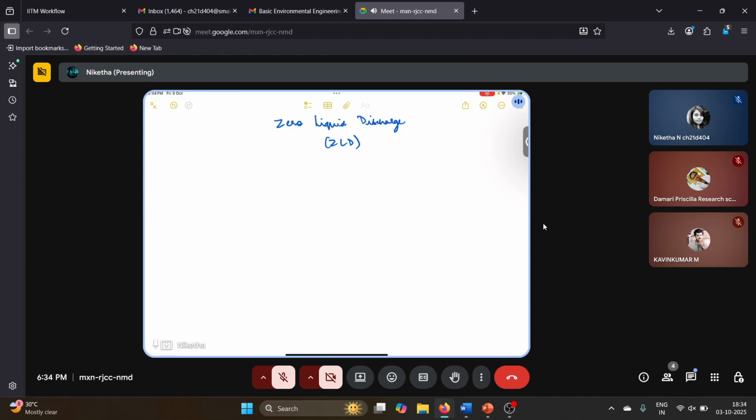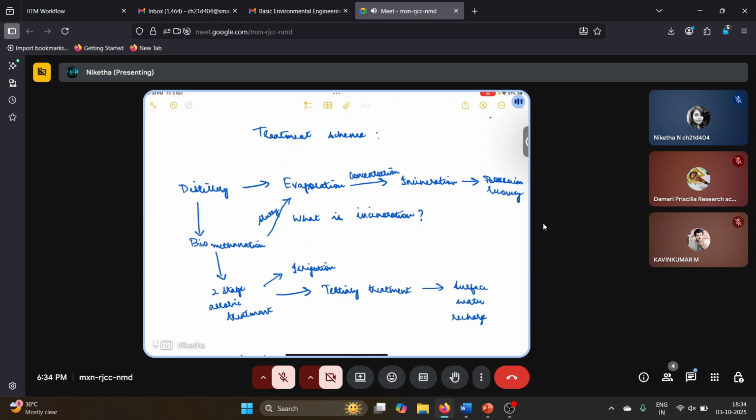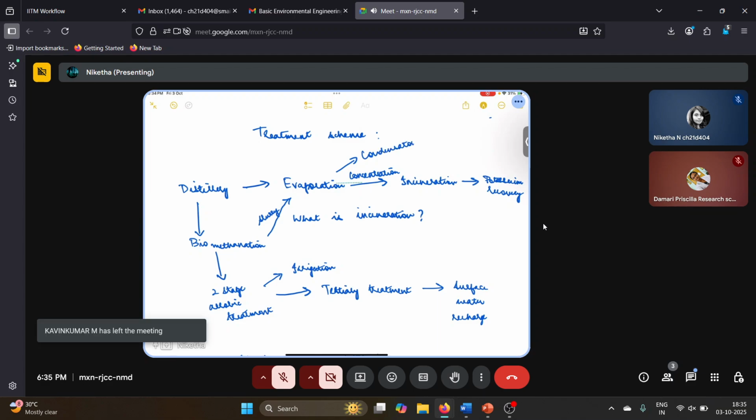Okay, then we have the condensate polishing unit. So here the feed from the condensate that we saw previously: the evaporator will also have, after evaporation, whatever vapors are generated, they will be taken to a condenser, and they will be condensed in a condensate polishing unit, or CPU.